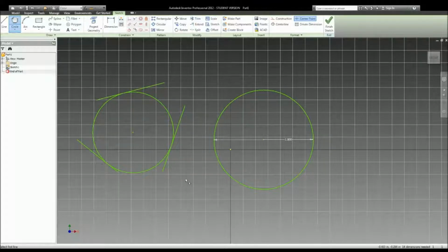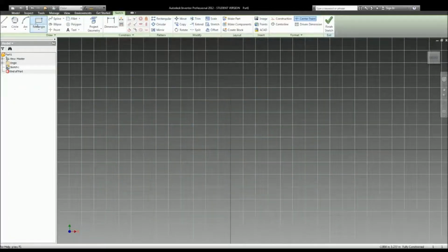Okay. So that obviously is for when you need a round object in a specific spot, and you don't really want to do the math to figure it out. You just can choose that option and just click the 3 points that the circle will be touching. And you'll get a circle out of that. Okay. Select everything again, delete.